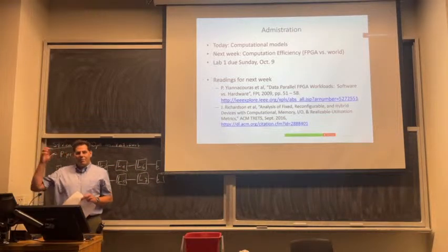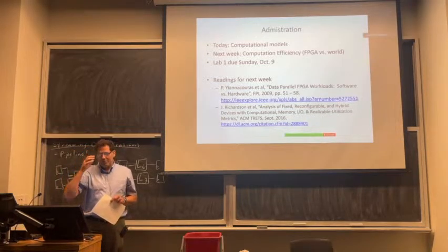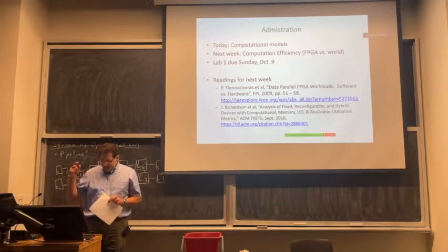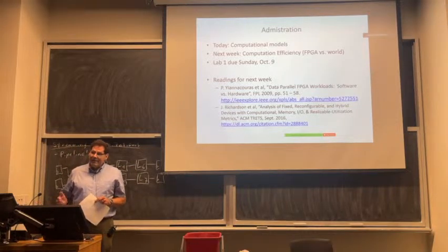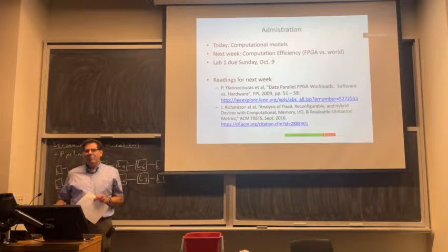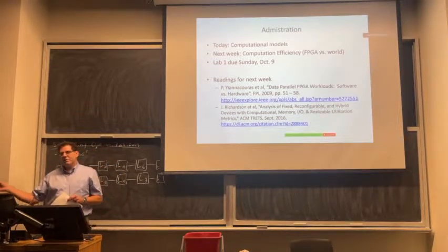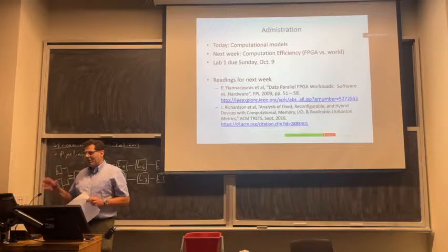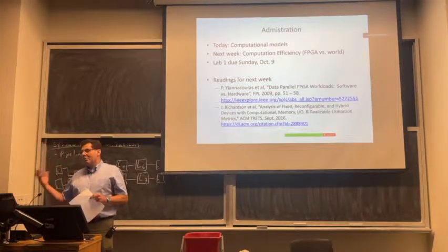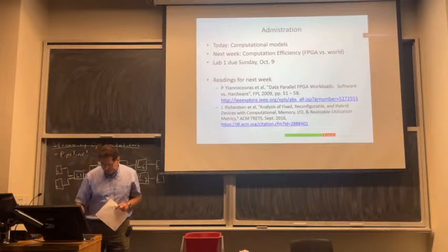What if I built hardware that did exactly one thing versus I had a processor do that computation? And then the second paper is an analysis of essentially peak numbers. How many multipliers, how much memory bandwidth, et cetera, can you get out of GPUs, CPUs, FPGAs? Now, you're generally not going to achieve those peak numbers, so it's not the whole answer, but they are informative. They help you think about what some of the guaranteed-not-to-exceed numbers are across those devices.